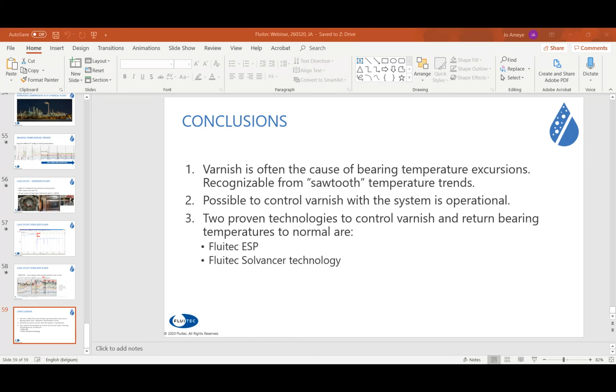The only thing you could possibly see, in some hydraulic systems, is that wear metals and other components that are sticking to the varnish can be released and then maybe foul your filters. But in the great majority of the cases we've done, we've never seen an effect on the filter.